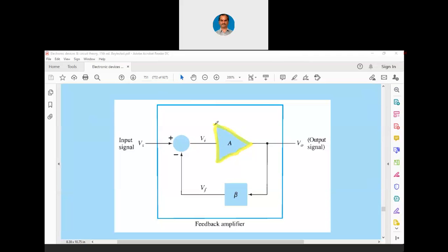So the answer is, let me stop annotating. I just showed you the amplifier symbol. The answer is, we have computed the input impedance as well as the output impedance for all the amplifier circuits. Ideally, the input impedance must be infinity and the output impedance must be 0. Now, we may not get that particular characteristic in any one particular amplifier. That is why we always club multiple amplifiers. So together, when we have a multi-stage amplifier, imagine, then the input impedance is very high and the output impedance is very low.